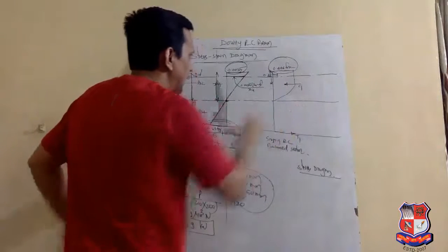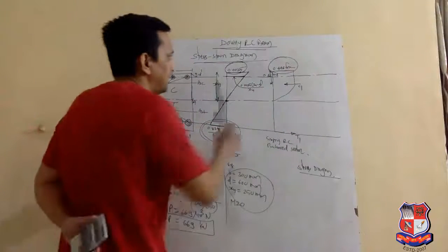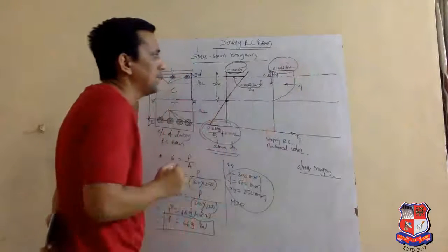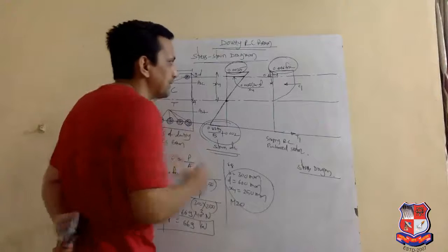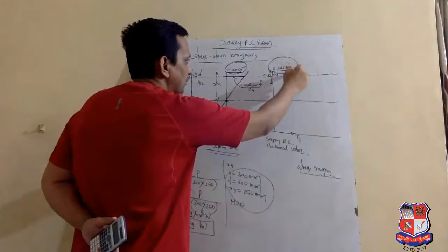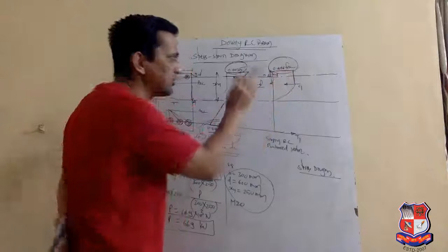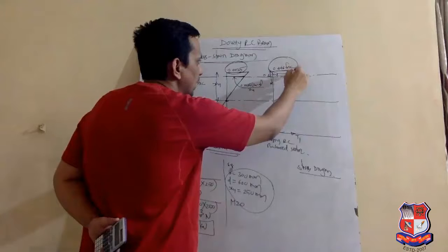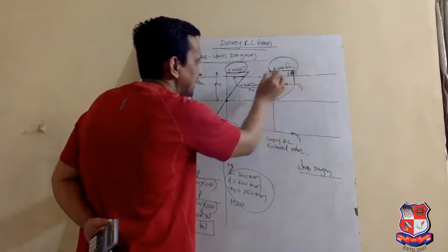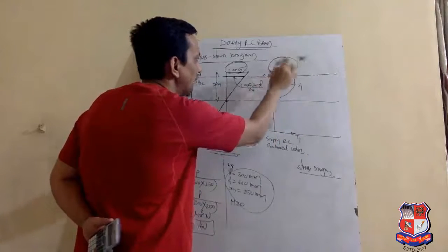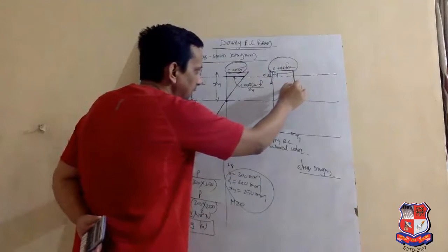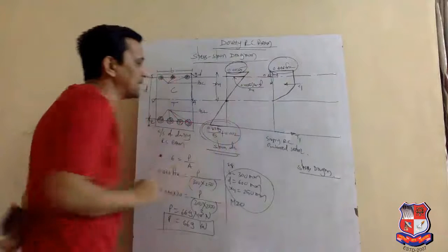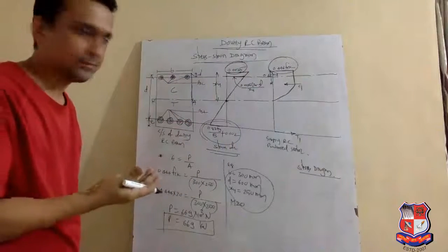Now, in this diagram, at the top of the beam there will be maximum compressive stress. When we go down, it remains constant, right? Stress will remain constant up to a certain distance, and that distance is 0.42 xu. Then it suddenly decreases and becomes zero at the neutral axis.